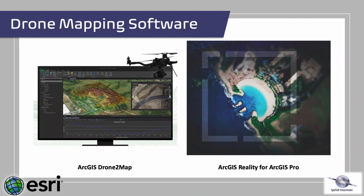It's simple: once you complete the flight in the field, go back to the office and create a project to download your drone imagery on your desktop, add ground control points, and automatically process to create 2D and 3D output. Then visualize and analyze by viewing 2D and 3D outputs. Make measurements, track changes, and perform other analysis with Drone2Map.